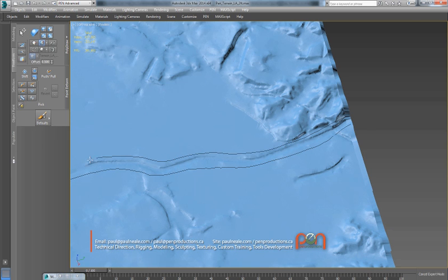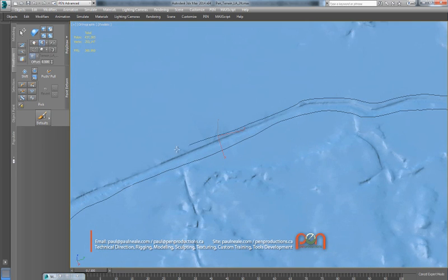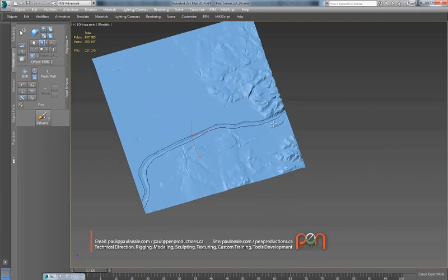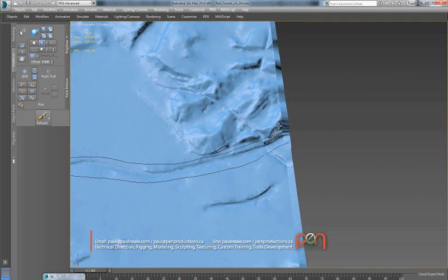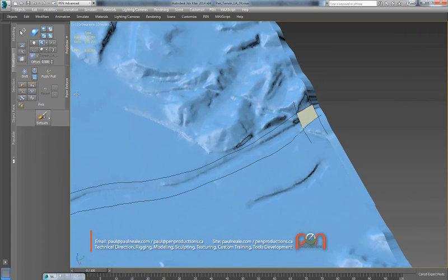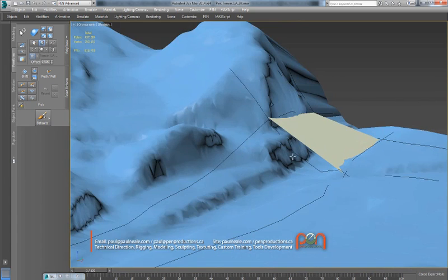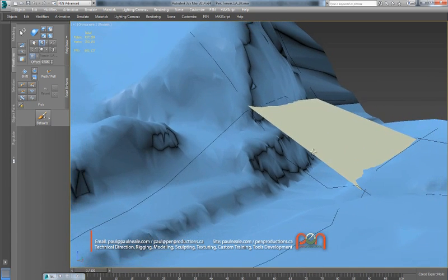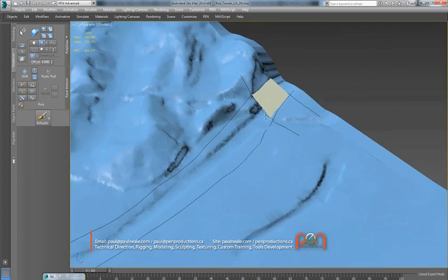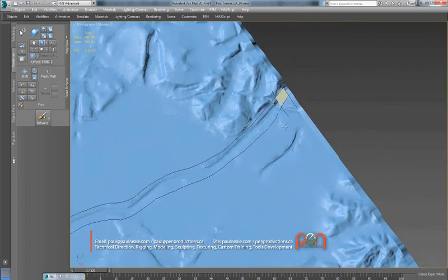If you notice, I'm not trying to be overly accurate. Hold down Shift again. Then we're going to start crossing over it, and every single time you make a square, you're going to get a new polygon. You'll also see that I've got an offset value, which is 0.5 right now, just to lift it off the surface a little bit to make it a bit easier to see.